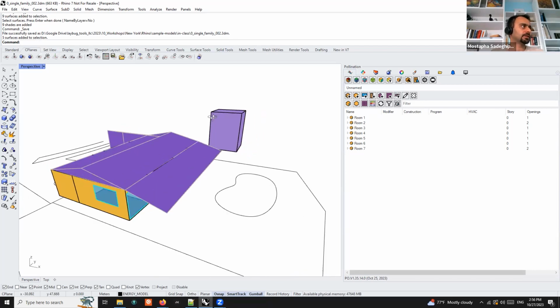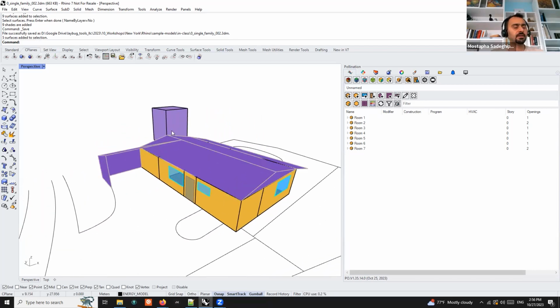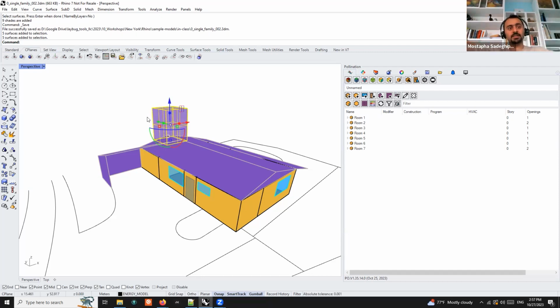There are two things. I think Chris mentioned one of them in the workshop in the morning. One is that the default material for them is different. The second is that for some code compliance routines or recipes, you need to keep the building shades, the ones adjacent to the building, but remove the ones that are other buildings on the site. If you're going to use your model there, these two types of shades matter. Otherwise, for a typical energy simulation, except for the default construction or material, EnergyPlus doesn't make much of a difference. They are basically the same.